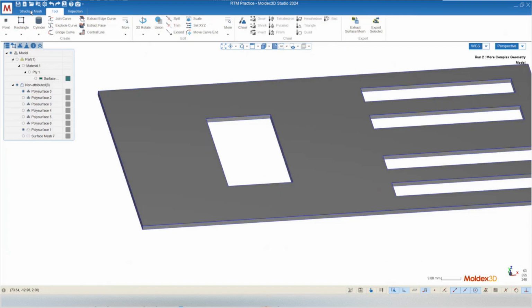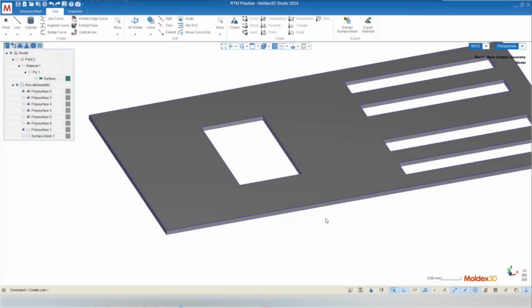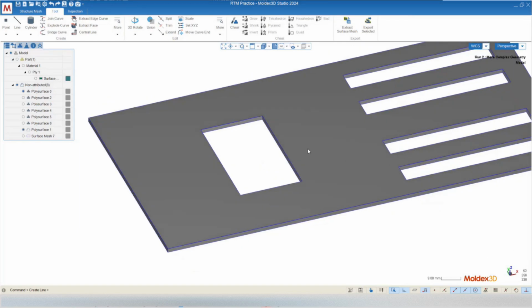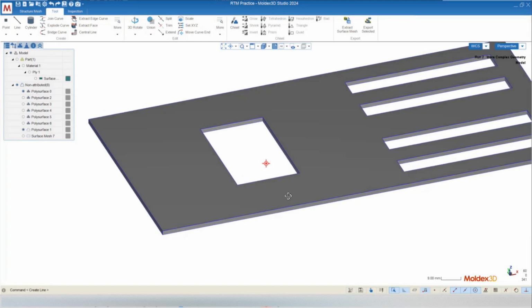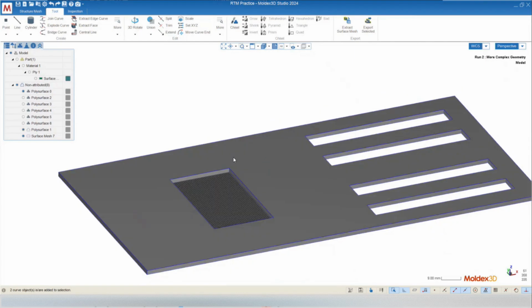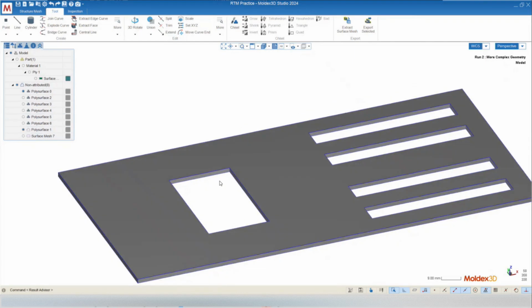So what I'll have you do is go from the structure mesh tab over to the tool tab. The second drop down over to the left, the first thing in that drop down should be a line. In order to do this line drawing, we're going to have to set up a bunch of references for ourselves, which isn't too difficult, but it does require us to have some snaps activated. Ultimately we'll have the 4 snaps active: end, midpoint, mesh, and perpendicular. Those are the 4 that we'll have toggled on, and that'll pretty much follow suit for the rest of this modeling.